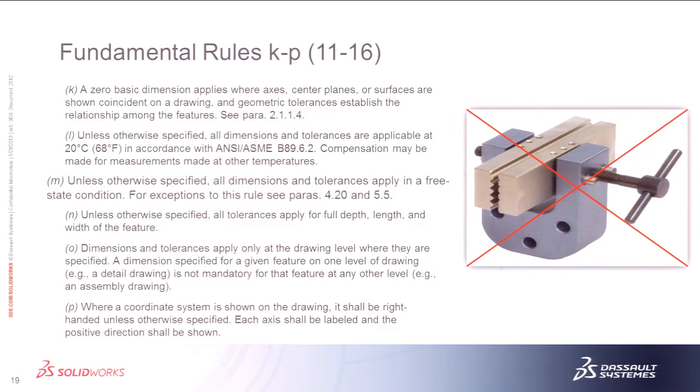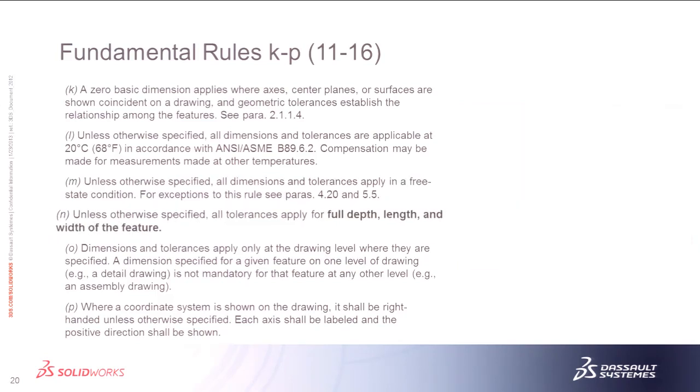Unless otherwise specified, all dimensions and tolerances apply in a free state condition, so the part isn't locked down and held in place. What about humidity? It's not in the standard. Yeah, I don't know of any reference to it. So when you're talking materials that are composites, that would be a big one. That would be something you would put in your notes if you need to control, make sure the humidity is controlled when they inspect the part. Put it in your notes of what it needs to be.